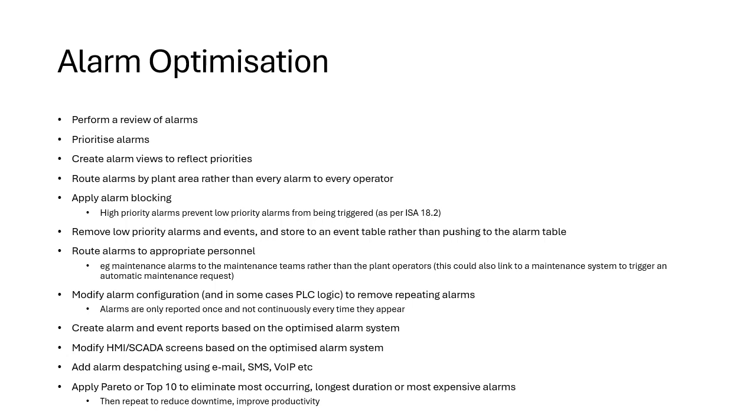So we could start off by prioritizing alarms. Maybe we've got critical alarms that need immediate action by the operator, but there might be other alarms which are low priority and which the operator doesn't need to immediately act upon. So you might get an alarm that warns you that the tank level, as we mentioned earlier, is going above 90%, but it's not reached 95% yet. That's maybe a worthwhile alarm to track, because if it keeps happening, that could indicate that your tank level is getting too high. On the other hand, if it's just getting above 90% but not reaching 95%, maybe your alarm limit is set too low and you may want to increase your alarm limit to reduce that alarm from occurring.